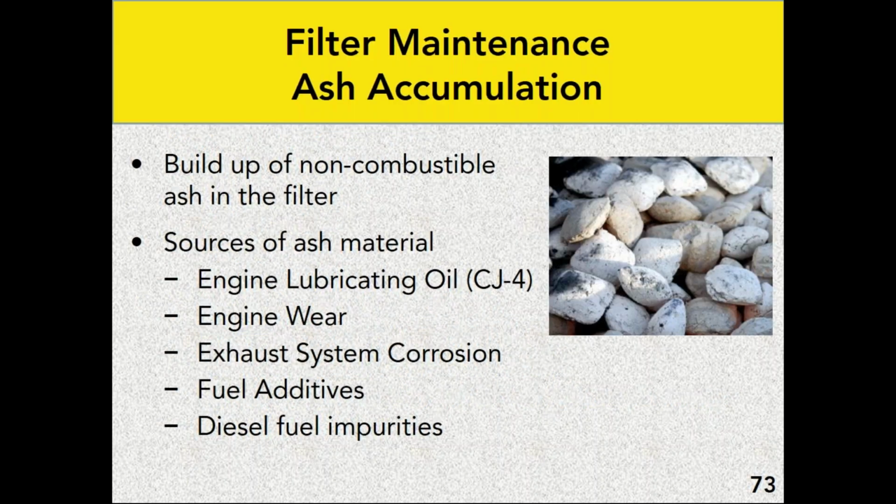It's normal. When you get a filter installed, whether it's OEM or retrofit, one of the things that you want to make sure you use, because most OEM filter manufacturers and practically all retrofit filter manufacturers require you to use an oil called CJ4, which is particularly designed to reduce the level of ash accumulation in the actual filter itself. And I need to explain that because of what we're talking about here.